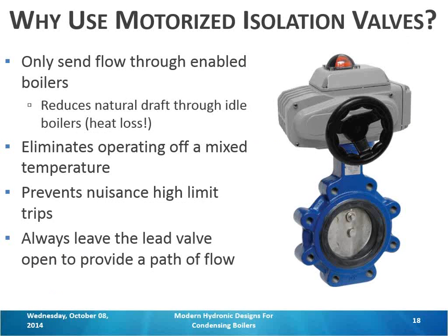The more stages you add, the higher that water temperature has to be, and then it'll lock out. Drops out of the sequence, boiler 2 comes on, same thing happens, that locks out, goes all the way down until every single boiler is on its safety alert.